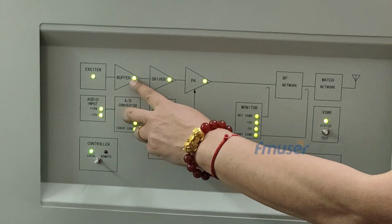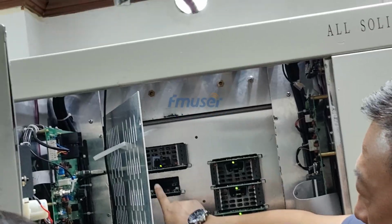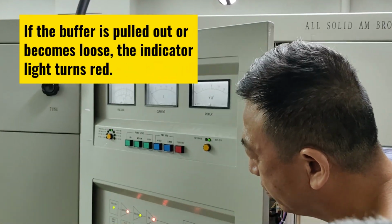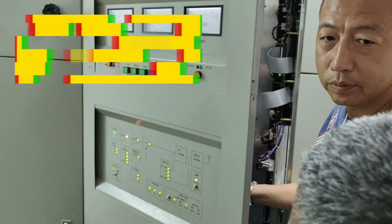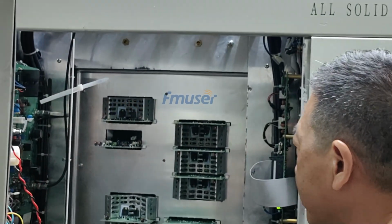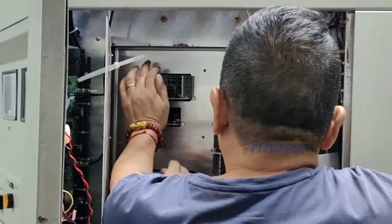AM transmitter. Buffer troubleshooting. The buffer module is responsible for boosting the signal generated by the exciter and preparing it for further amplification. In case the buffer amplifier board becomes loose or is pulled out, the monitoring panel's buffer indicator light will turn red. This serves as a visual indication that the buffer module is not functioning properly and prompts the operator to check for any loose connections or issues with the board.